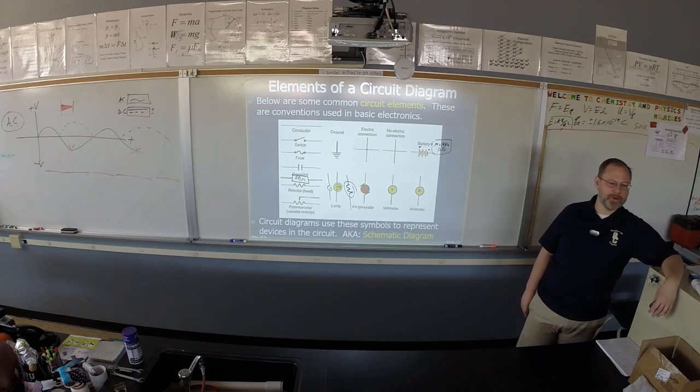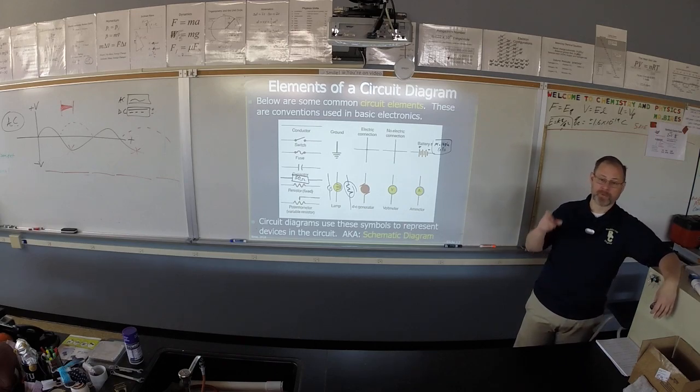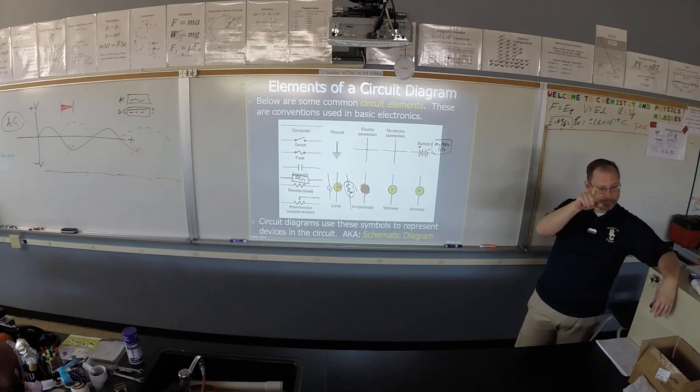That's how you think about it. A battery is multiple cells. A 1.5 volt AA battery is actually not a battery, it's a single cell. The electrochemical potential is about 1.55, 1.6 volts. It's one single chemical cell. Your cell phone at 3.7 volts is one lithium ion cell.